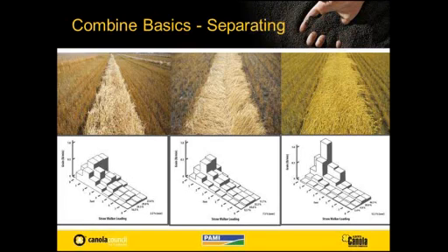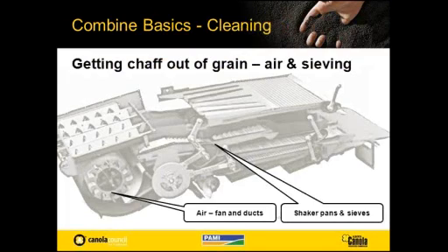So it's important to recognize this, because your windrows will change as you go around the field. And there are some things you can do driving. For example, you don't want to drive off center unless there's a good reason. If all the heads are on that way, you want to put the heads in the middle rather than off to the side. So you can't cure it, but you can help it out a lot by the operator driving and understanding what's going to happen inside of your combine as you're doing that.